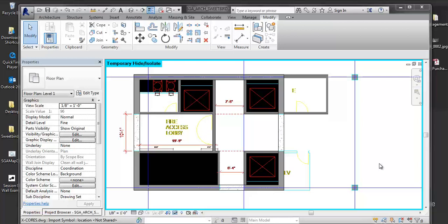I'm going to have this same core assembly up the entire system here, right? The core walls I know in real life are going to continue on through the slabs and all the way up. But if I approach building it this way, that means I'm going to have to go to every floor and copy up doors. So I'm going to think of this as a sandwich of items. Instead of having my walls continue all the way up to the roof, since this is a repetitive element that goes from floor to floor, I'm going to combine it into a group and then copy that group up from floor to floor, okay?